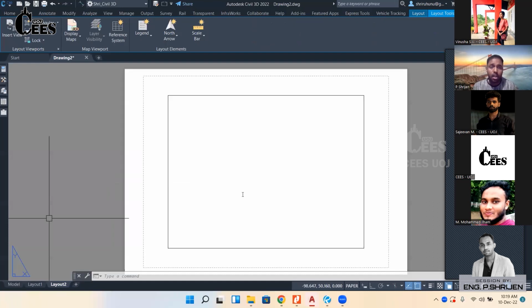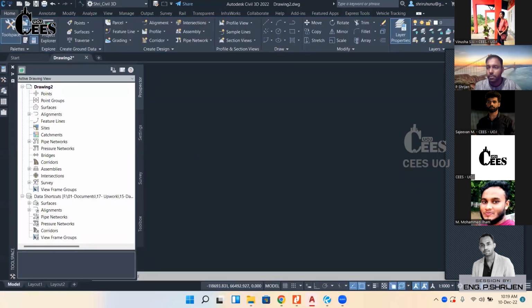If you like to work with the mouse, go to the View tab and you can find this button for the tools. It will show you a tooltip. In the tooltip, you can find the tool name and the shortcut. You can see Ctrl+1 accesses the Properties. So like that, one of the important tool palettes is Properties, and the second one is Layers.